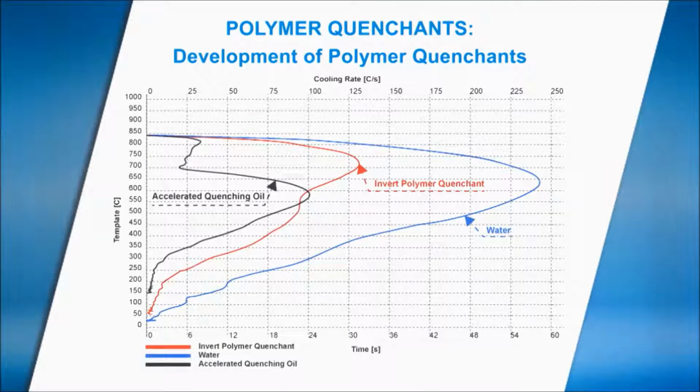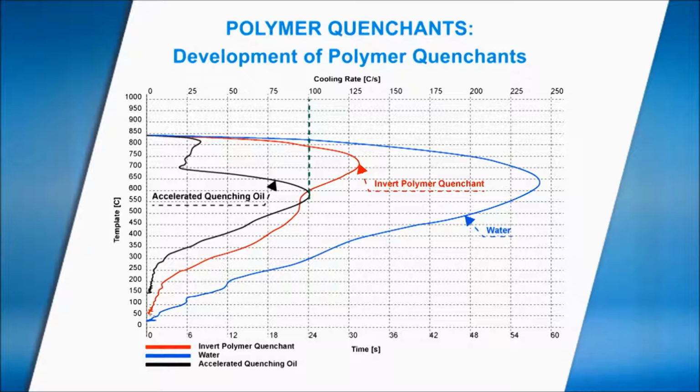As has been shown, quenching oils cover a wide range of cooling performance, yet there is still a significant gap between the maximum achievable cooling rate of a low viscosity accelerated oil and that achievable with ordinary cold water. Water-miscible quenchants, which fill this gap, are thus an ideal complement to the quenching oil range. Heat treatment operations can be carried out with these water-based quenchants which would either be impossible or extremely difficult with oil. This particularly relates to spray quenching in induction and flame hardening processes, where a high degree of fire risk exists when using oil.